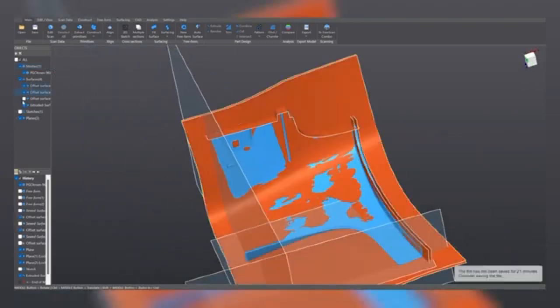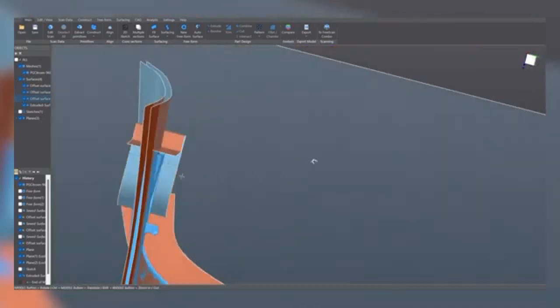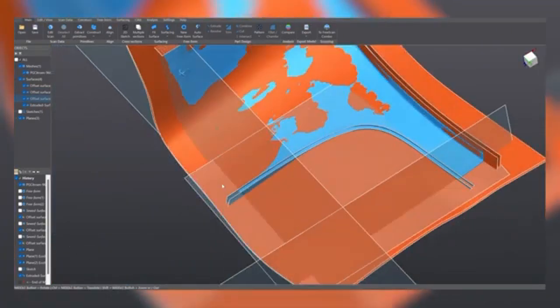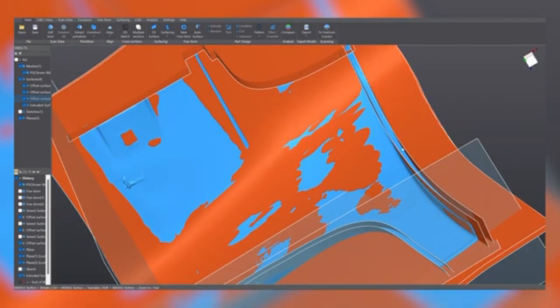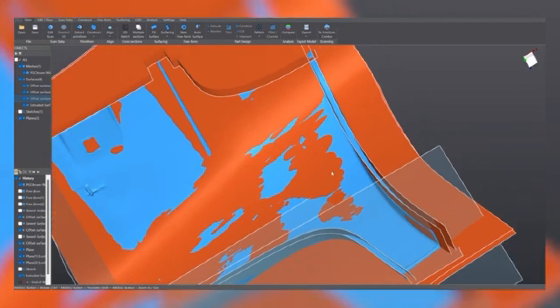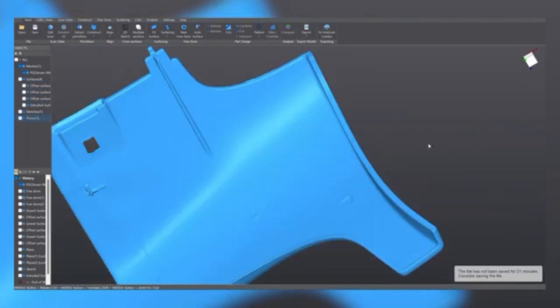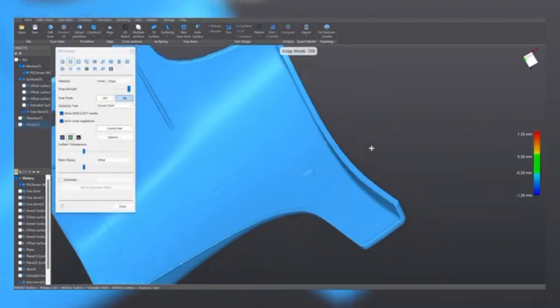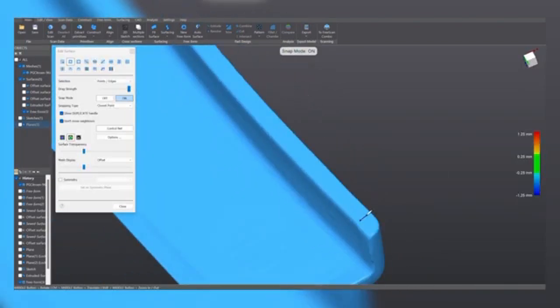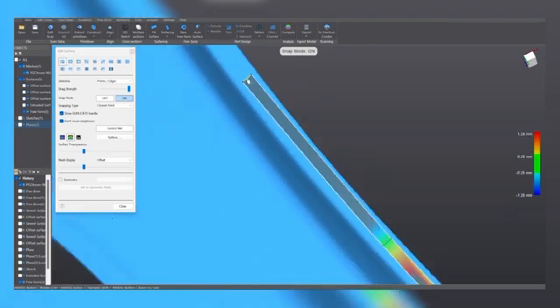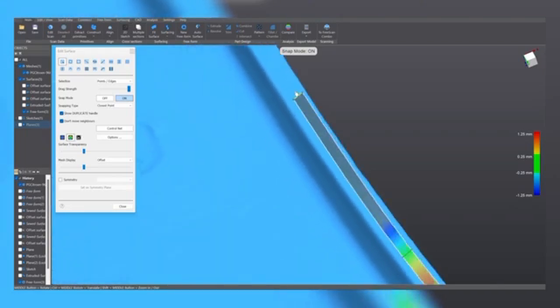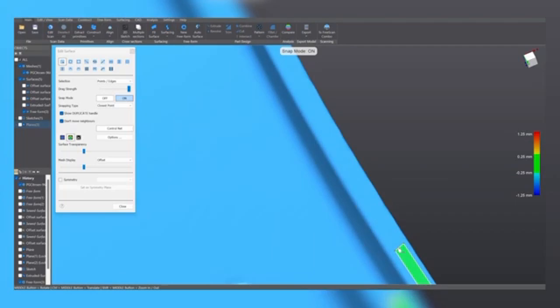And let's see what's left. So our surfaces will close here. They will close here, here as well. Oh, we need to reproduce this shape here, this face here, to close these 2 surfaces. And this we are going to do it with a freeform. So again, let's hide everything, also the planes. And you know the process. We create quickly a new face here, update the view, and extend it. Always snapping on the mesh.